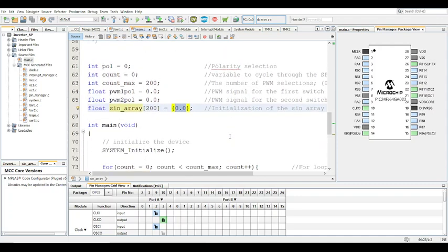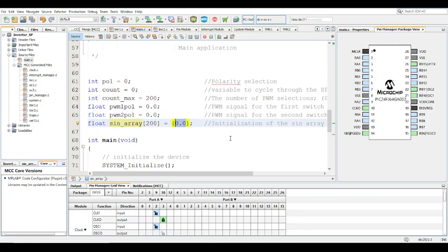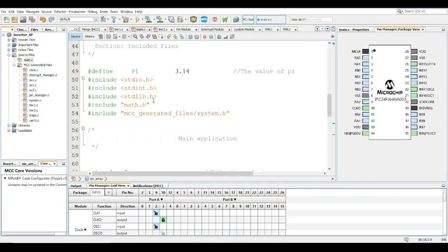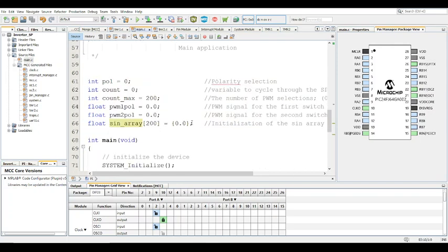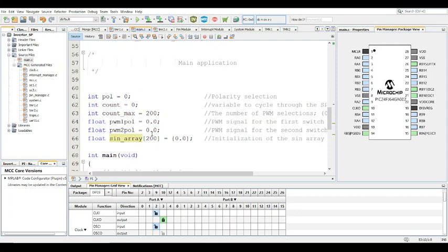And there are actually two ways of doing this, right? You can calculate using the sine function. Obviously, you have to use the math library, and you can calculate each time. So in that particular interrupt, for each PWM, you use the sine function to calculate the required PWM each time. But that actually takes a lot of time, because the sine function takes time. So it's better to calculate the entire sequence, the entire array, first.